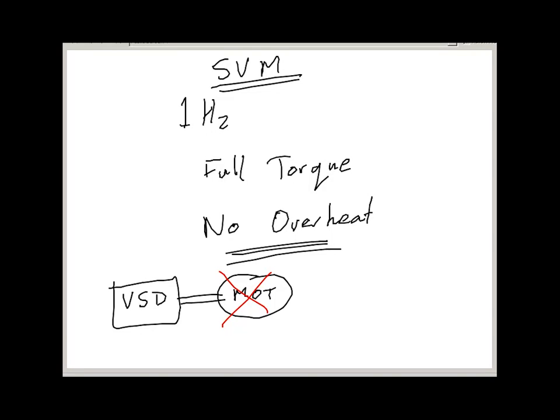And so this system, called different things by different manufacturers, but effectively what we're doing is we're changing the voltage to change the magnetization so that we don't over-magnetize. If we make sure that we don't over-magnetize, then we don't overheat, because we don't put the extra energy in in the first place.